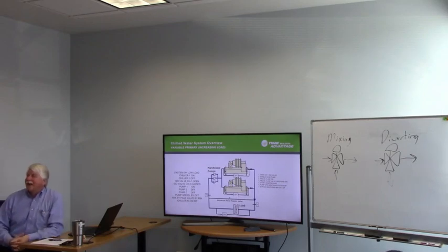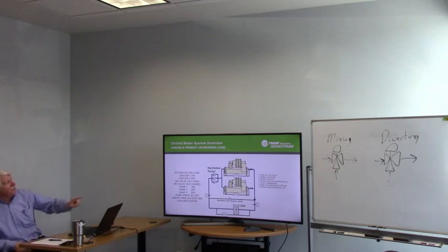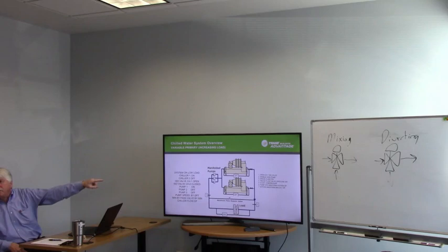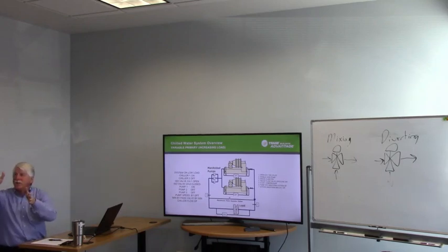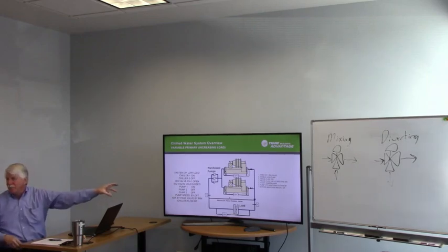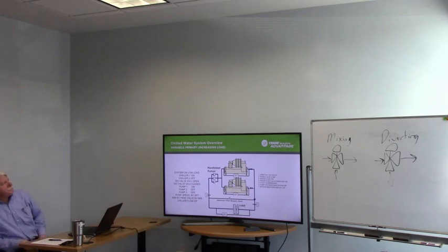Then we use a secondary proof of flow. And the secondary proof of flow is typically an end switch on the valve. Okay? So we won't let the chiller start until the valve gets to its 100% open position and the IFM makes, okay? So once we've got both of those done, the unit will start up the compressor. And at that point, the pump maintains the system VFDs.